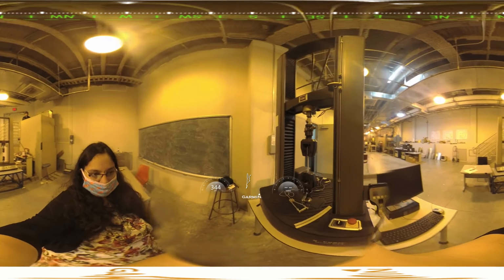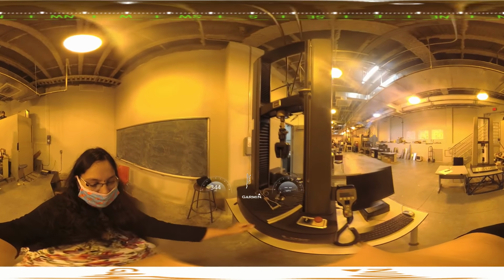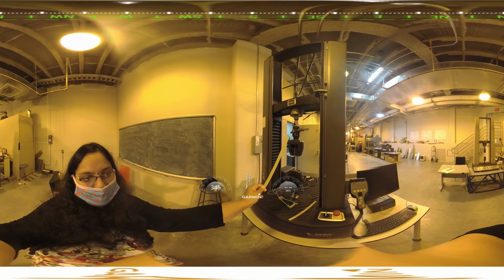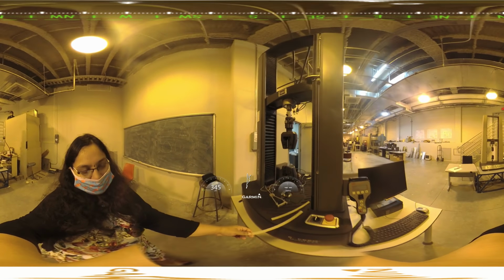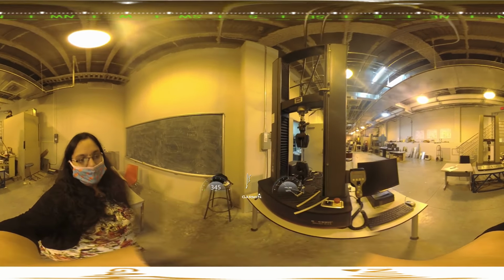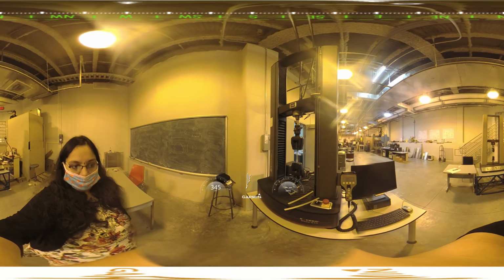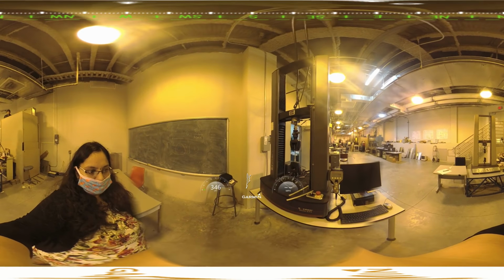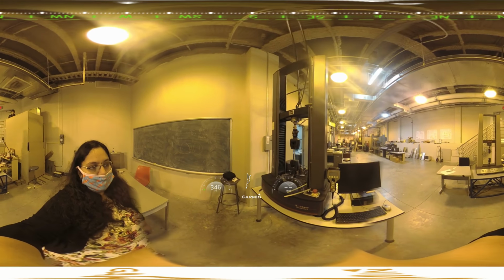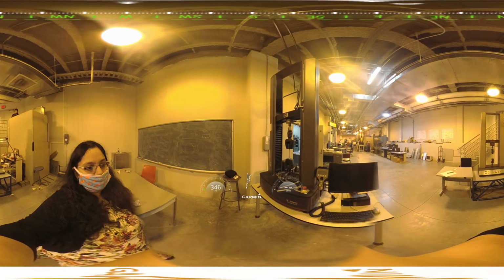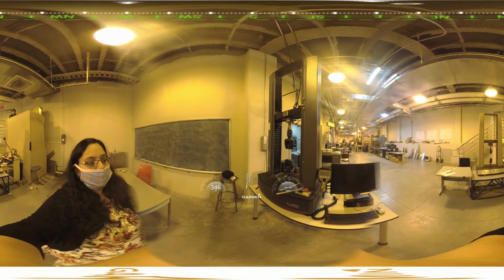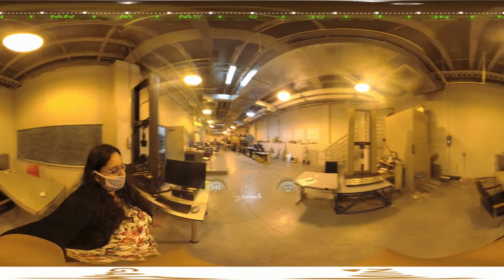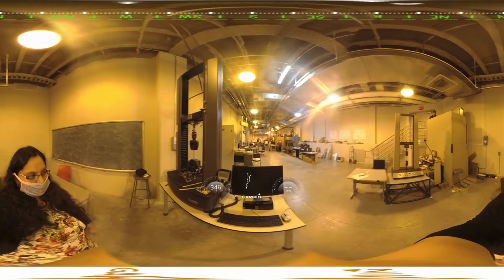We are also going to use the composite that was manufactured using prepreg from the VARTM lab, and we are going to mount it similar to the dog bone specimen and study the Young's modulus and ultimate tensile strength. And we are going to do a statistical analysis for different types of alloy and also a statistical analysis on the composite itself. This is an overall view. There are multiple tensile testing machines here which are used for different purposes.